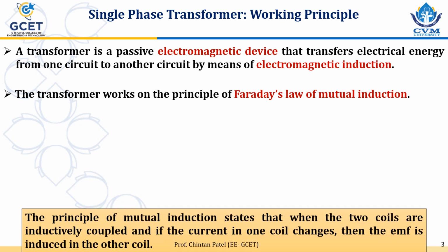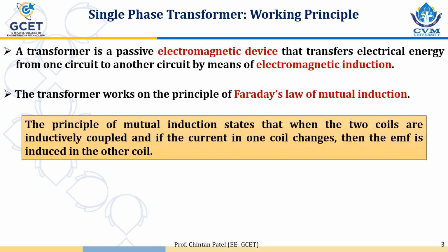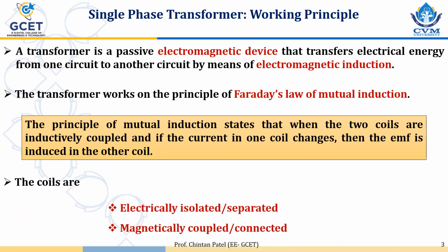What is mutual induction? The mutual induction is when the two coils are magnetically or inductively coupled or connected, and if the current in one coil changes, then the EMF is induced in the other coil. That means these two coils are electrically isolated.